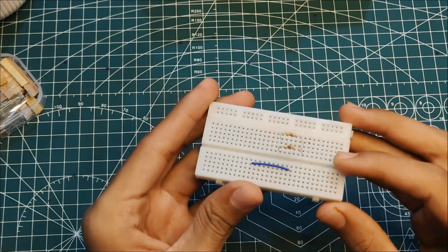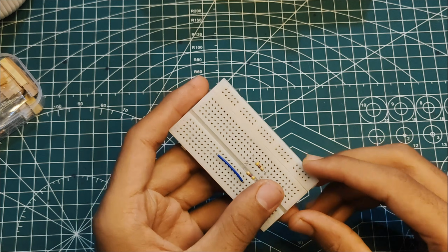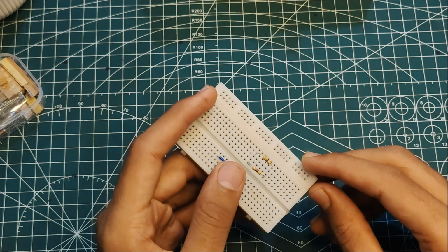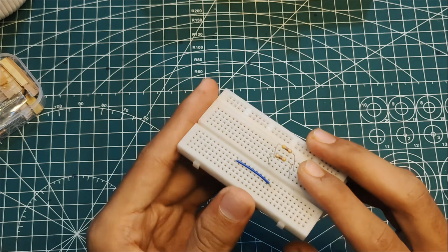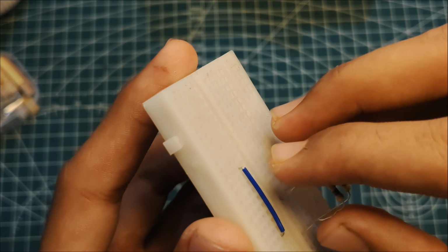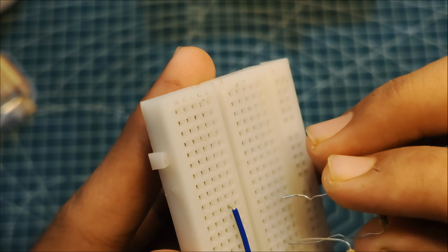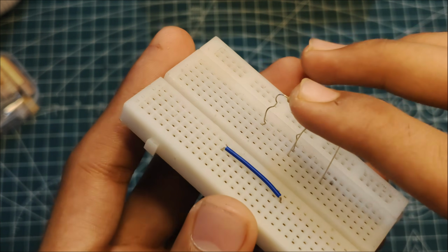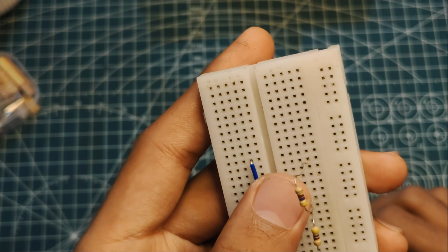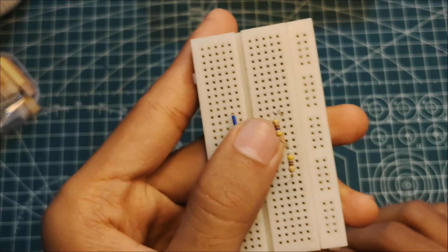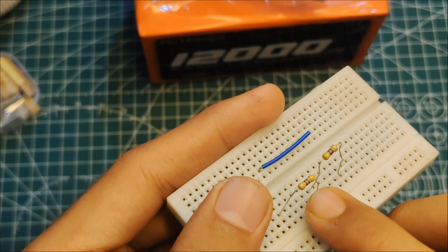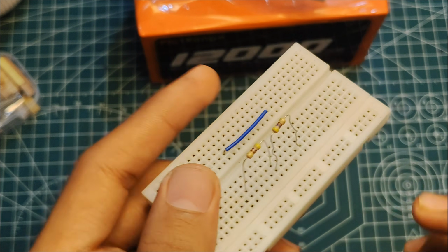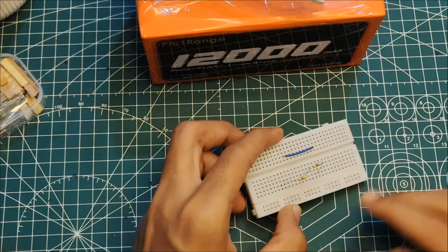Now, another application of resistors is to use them as a voltage divider. I have already told you the circuit for that, and right now we have our resistors, which have a value of 450 and 450, which we have already tested. We are going to use these exact resistors to divide a particular voltage into two parts. We have already seen this when we demonstrated the voltage across each of these resistors connected in series. Let's try to do that exact thing again.